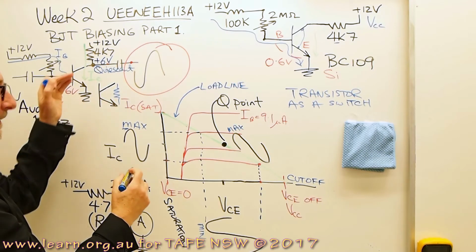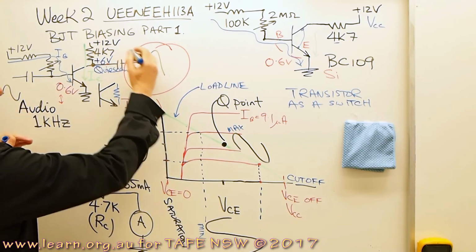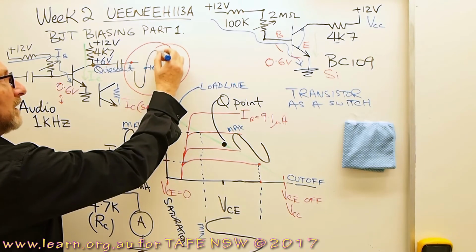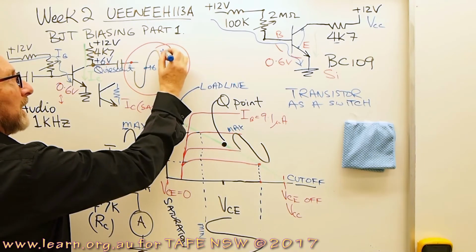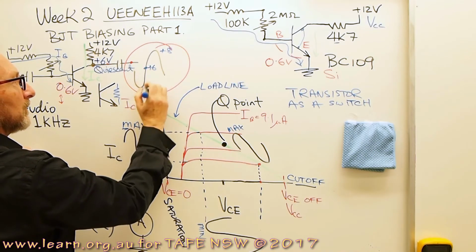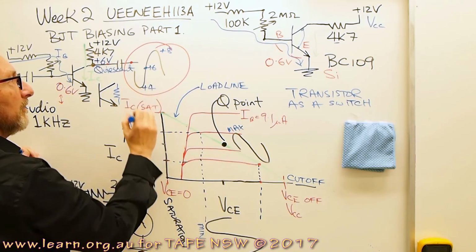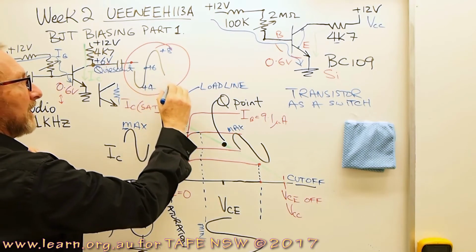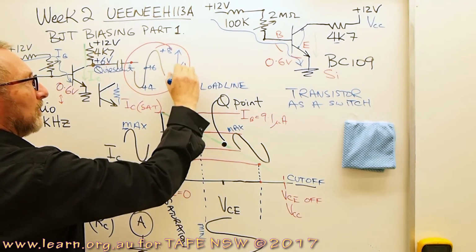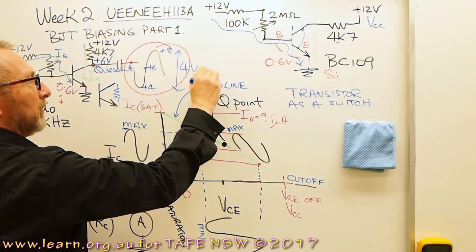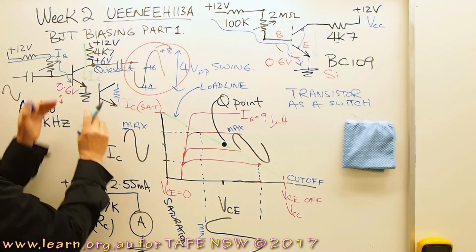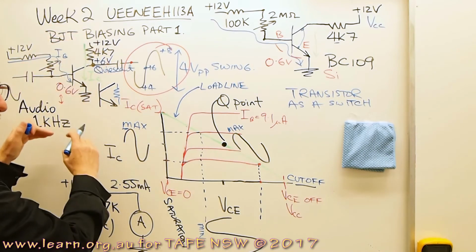That way, that 6 volts can go, let's say here's 6, plus 6, we could go up to say plus 8 and down to plus 4. So we could have a 4 volt peak to peak swing and we won't hit the rail and we won't hit ground.